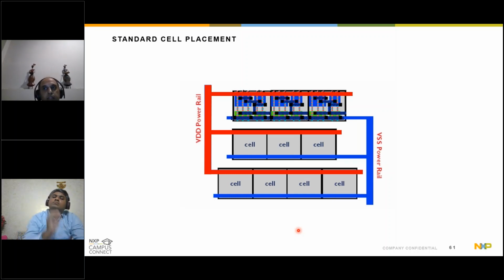So he will use the pre-built standard cells, and those standard cells are encapsulated in certain library formats. Let's say the LEF and the DEF, library exchange format and design exchange format, that define the physical view, and then Synopsys, let's say, Liberty formats that define the timing view or the power view of these standard cells. So this goes as an input to the synthesis tool, and ultimately the synthesis tool will give you the netlist.